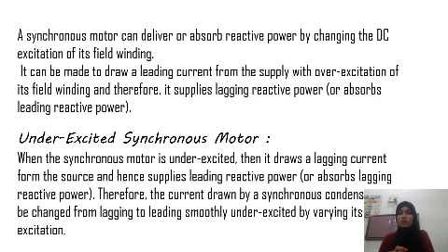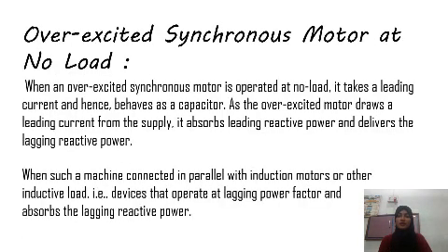When the synchronous motor is under excited, then it draws a lagging current from the source. Hence it supplies a leading reactive power or absorbs a lagging reactive power. Therefore, the current drawn by the synchronous condenser can be changed from lagging to leading smoothly by varying its excitation. Another one is the over-excited synchronous motor at no load.